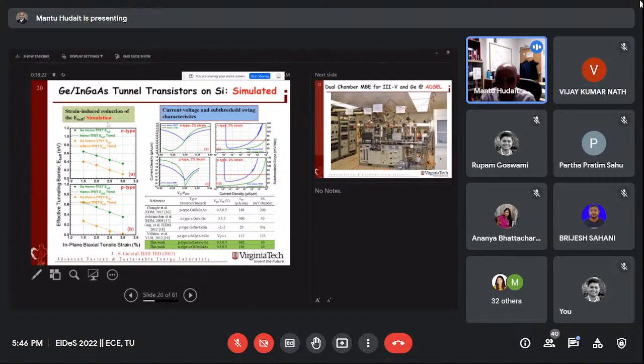So very promising. And you see that germanium on InGaAs is under tensile strain, meaning the percentage you see here, the strain that you give, makes the germanium band gap become direct. Around 1.65, the germanium is a direct band gap, because the gamma point, the heavy hole and light hole, are on the same line. And I have some band structure slides I'm going to show you when I talk about photonics. So that is very cool stuff. Can you make a direct band gap germanium? Is it good? Yes. What can I do?